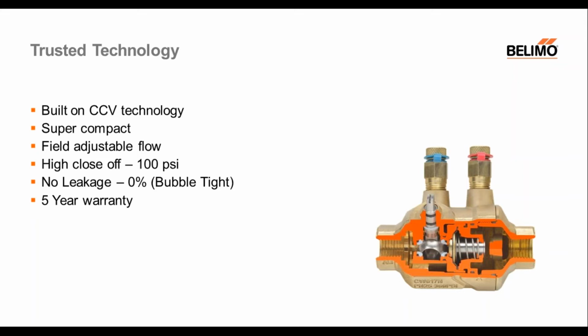We've designed the valve and actuator combination in such a way that in the field, you have the possibility to adjust your flows depending on the coil's GPM. So what I mean is, you buy a PIQCV with a nominal flow of X, and when you get to the field, you need a different flow, a smaller flow than the nominal flow of the valve. And while you're in the field, you have the ability to adjust the flow to match your coil's GPM requirement.